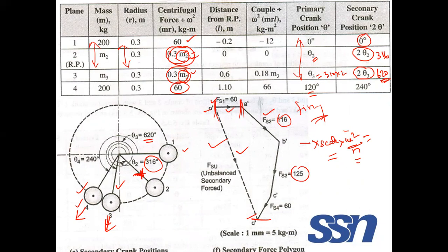So here we have taken some dimensions, some mass, some radius, and some theta value and firing order. You can vary this according to a requirement. That is up to you. You vary and find the perfect combination that will give minimum unbalanced forces and couples. You can try.